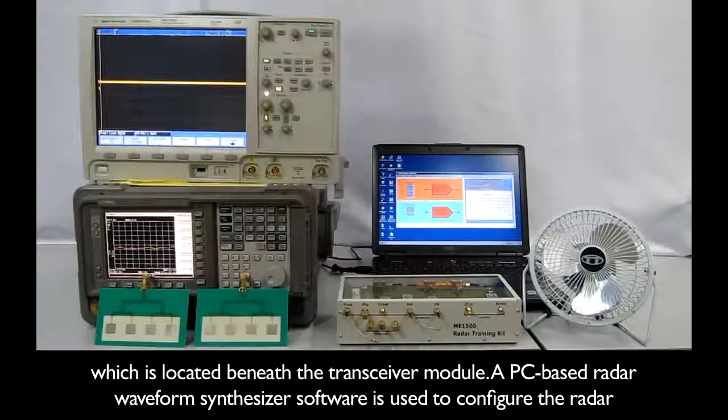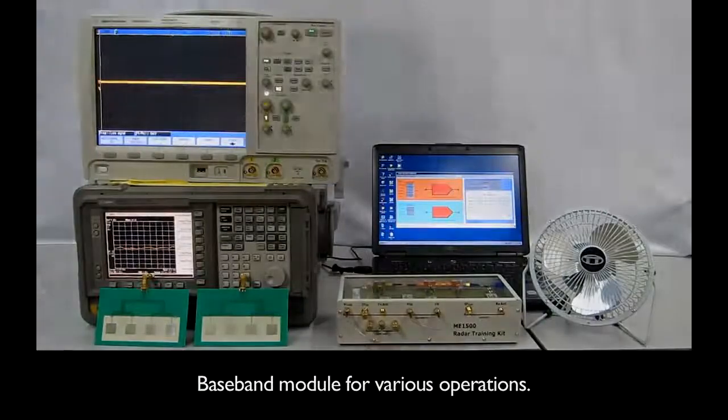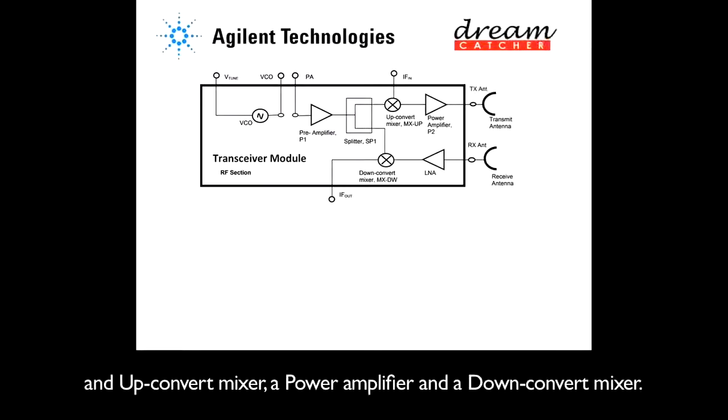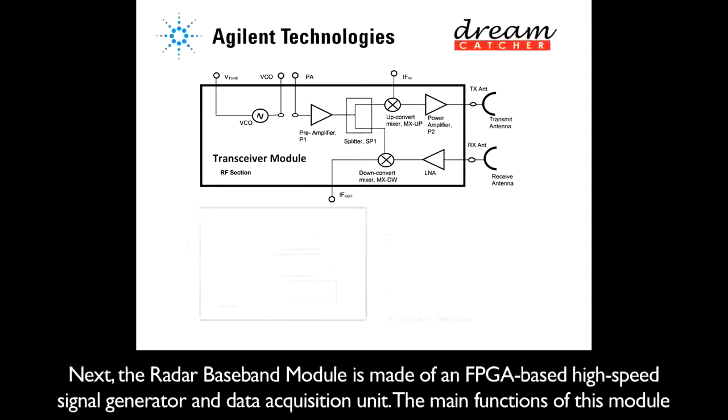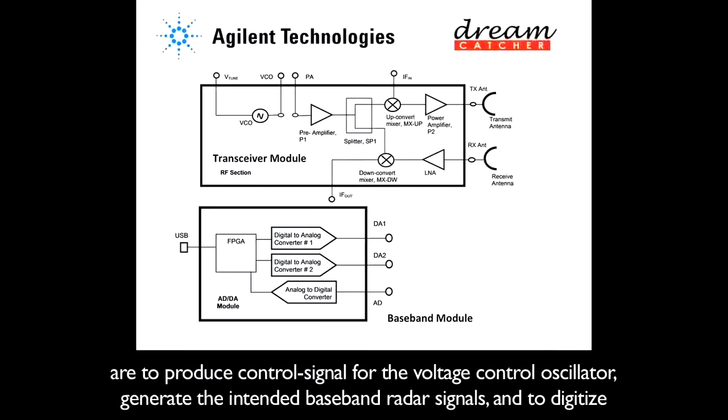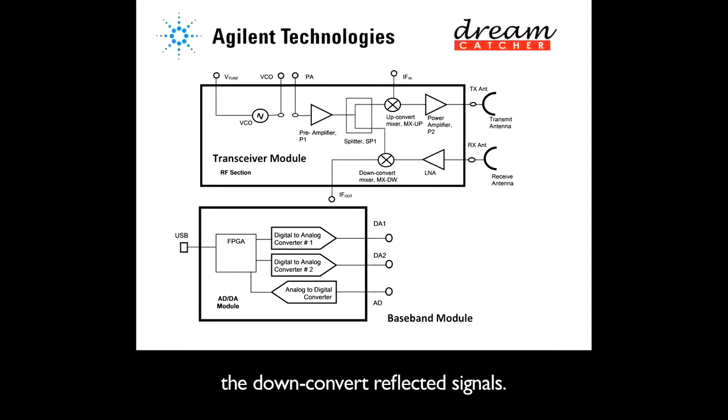A PC-based radar waveform synthesizer software is used to configure the radar baseband module for various operations. The radar transceiver module is a super heterodyne system consisting of a voltage control oscillator, an up convert mixer, a power amplifier, and a down convert mixer. Next, the radar baseband module is made of an FPGA-based high-speed signal generator and data acquisition unit. The main functions of this module are to produce control signal for the voltage control oscillator, generate the intended baseband radar signals, and to digitize the down-converted reflected signals.